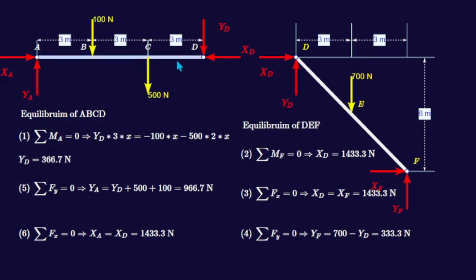It is crucial to begin by identifying an equation with a single unknown, as this simplifies the analysis. This approach is typically applicable when two pins are aligned either vertically or horizontally within the entire frame or in its dismembered members. Take note of the order of steps in our analysis, as it helps minimize the time required to solve the problem.